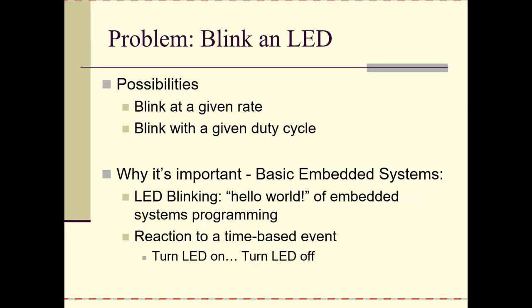When you talk about blinking something, there are two possibilities here: the rate at which you blink it and also the duty cycle. We don't necessarily need a 50% duty cycle when you blink something. The blinking LED is the classic hello world of embedded systems. Essentially, if you can get an LED to blink, that means you've got your hardware talking to your software. I know it sounds kind of wimpy, but it's actually very effective to get an LED blinking.